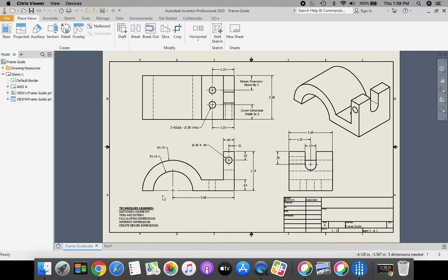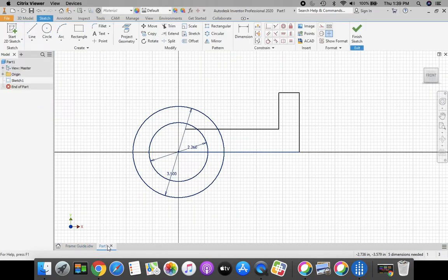And the width from the origin out to the side is 3.5. So let's enter in those dimensions. To do that, we're going to come up and place a dimension. I want a dimension from the origin out to the side, so I'm going to click my bottom line.